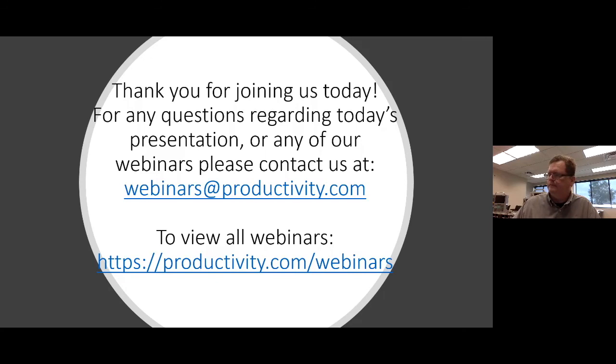Carl is asking, if you were to probe a bore or hole that had a keyway at 90 degrees, is there a way to do a 4-point probe and rotate it 45 degrees to make the machine probe at 45, 135, 225, and 315 degrees and miss the keyway?